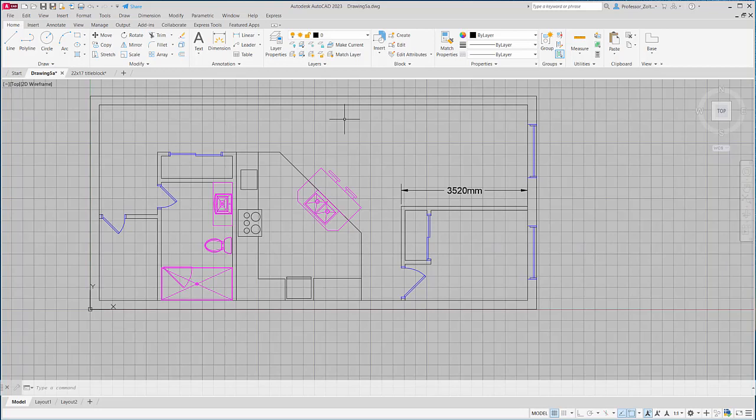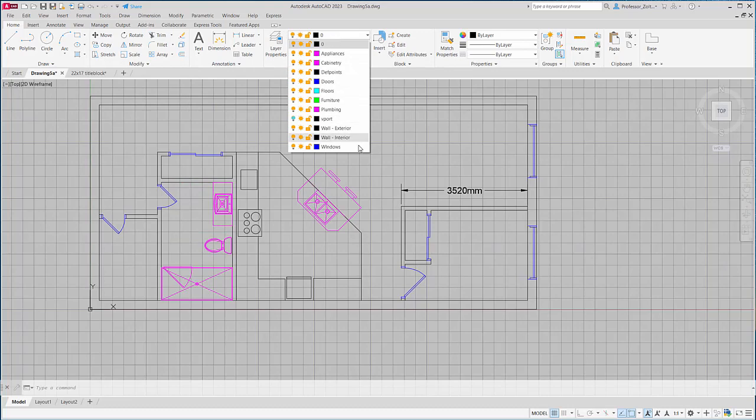So this next step sequence is to hatch or fill in some of the information so that it looks more like a presentation drawing. So this is our hatch symbol. Now, you'll notice I'm in layer 0. And hatching is kind of unique. You'll see as we go through this. I can actually create my own hatch layer and make sure everything's on there. Or it will place the hatch within layers that are currently present.